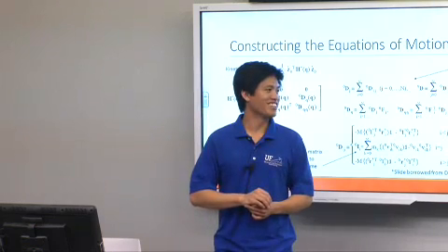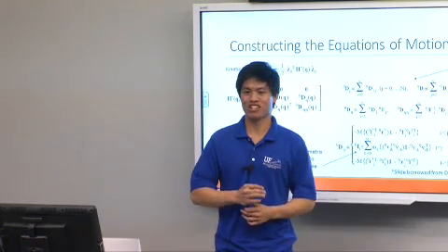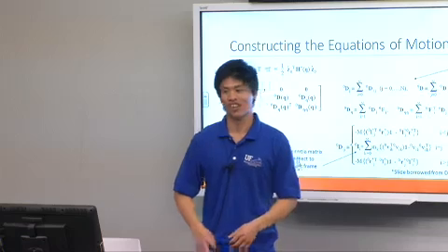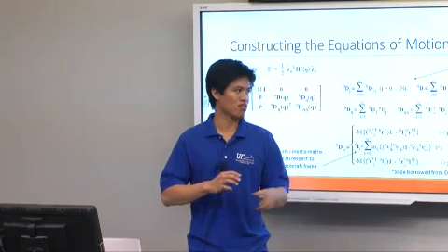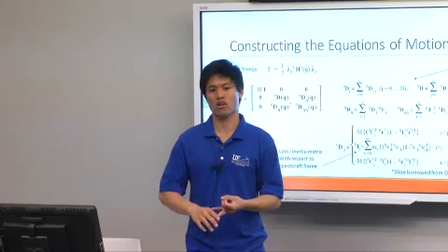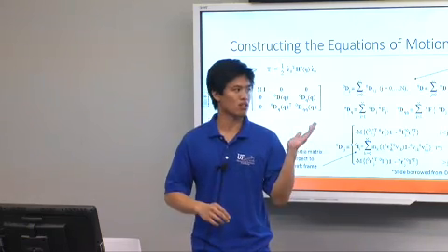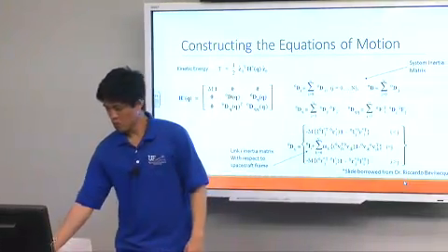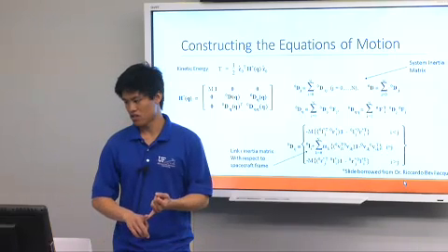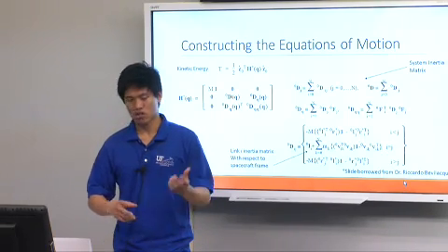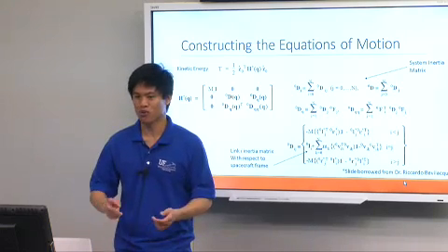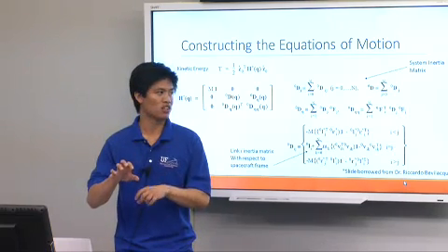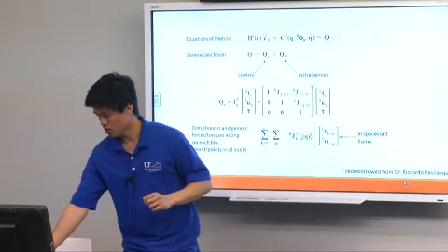So basically, if you go through all these summations and construct the matrix as such, this matrix encompasses the entire definition of kinetic energy. It's the translational part and the rotational part. And so it's a scalar quantity, so when you multiply that all out, it's very long. So what is Z0? That's our independent, that's our state vector. Those are, well, it's quasi-Lagrangian because, and I'll go over why that's a technicality, we use Lagrange's equations for a certain portion of the equations of motion. So I think that's the next slide. Okay, so I'll go over that soon.